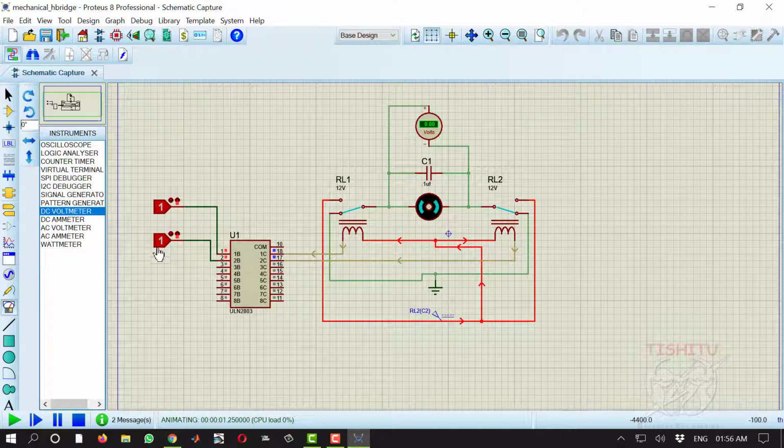Okay, in the circuit these two are getting 1 in position, and when I put 0, it moves in a clockwise direction. And if it is in 0 state, then in the whole circuit there is only a positive supply, so there is no reference potential across the motor, so it will not run. Whenever there is a change in the input signals, it will start rotating accordingly, clockwise and anti-clockwise. Now it is running anti-clockwise with a potential of 11.8 volt.